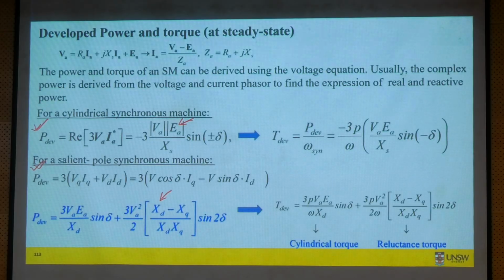But why we don't often use this equation is that we need to know this angle delta, right? This load angle. When we control a PM machine, we don't control the delta angle. We control rather the current angle, okay? So that's why these two equations are not often used, especially in control space, and they are also steady state equations. As you know, they are valid only for steady state condition. They cannot handle transient conditions.